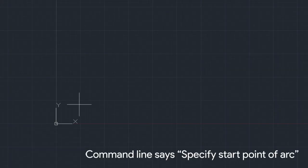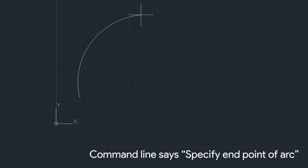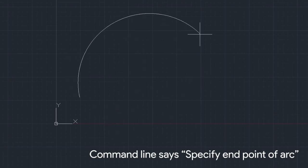You have two options in specifying your starting point. First is coordinates, and second is just to choose the desired location you want. I will choose the second. I just click anywhere. Click. Now your command line asks for the second point of your arc. Since we are not using coordinates, we are just clicking everywhere. Second point, click. And then now you have an arc, and it is asking for an endpoint.